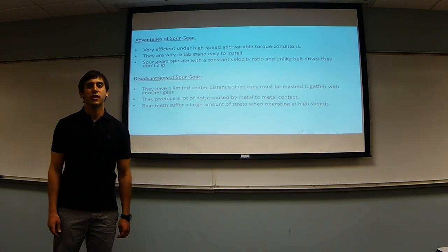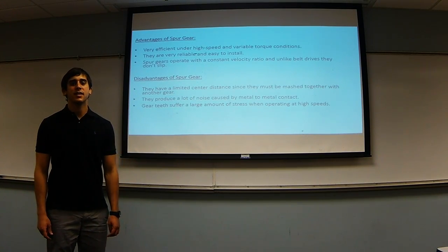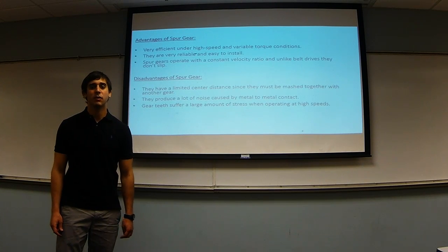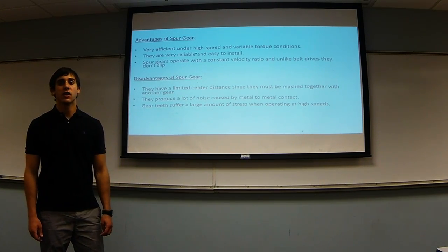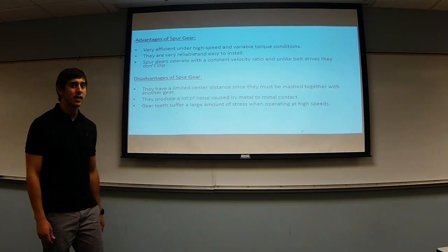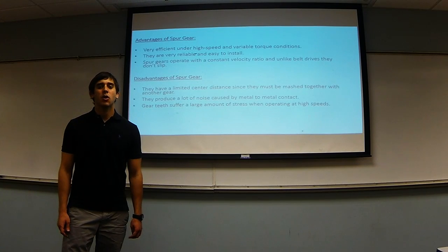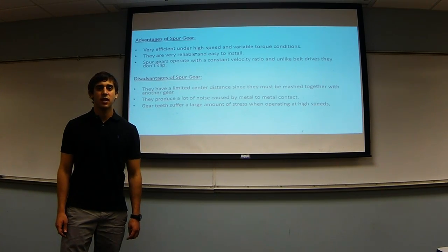Disadvantages of a spur gear. They have a limited center distance, so the system must be meshed together for another gear. They produce a lot of noise caused by metal-to-metal contact. Gear teeth experience a large amount of stress when operating at high speeds.